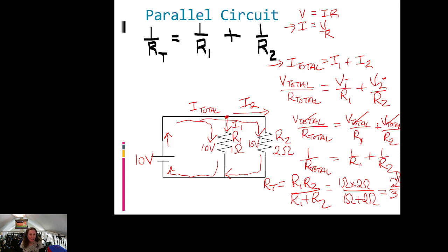It really is. So I'd like you to just sort of think a little bit about how this works, that the current gets split off, just like water, a fork in the river sort of thing. But the energy part of it, the voltage, stays the same going to either part of the fork. And then if you have to add up the resistances, it's different. In a series, it's really simple. You add them up. If it's in parallel, you have to do it in this fraction way. So if you sort of take that little bit away from this, fantastic. If you get the math, bonus, but I really don't expect you to get the math at this point.